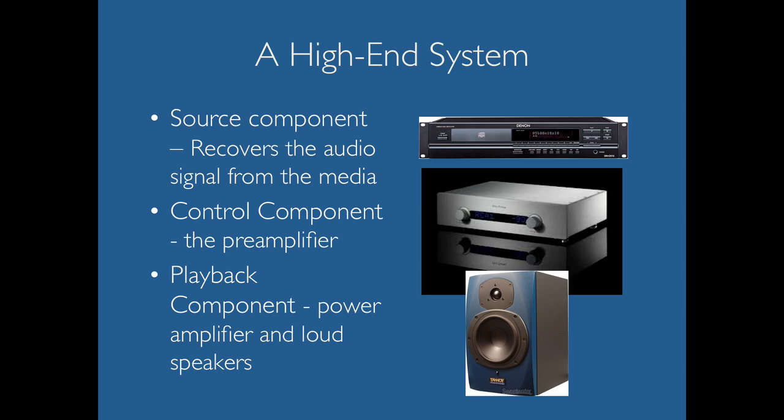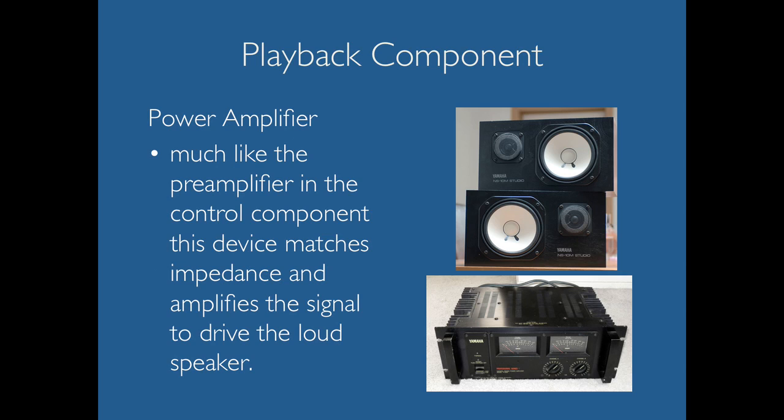So this could be both a power amplifier and loudspeaker, or it could be active speakers that have their own power amplifier within them. I show this picture of the Genelecs down here at the bottom. They are active speakers. They actually have a power amplifier within them. So power amplifier, much like the preamplifier and the control component, this device matches impedance and amplifies the signal to drive the loudspeaker. The Yamaha NS10s, as you can see here, a sort of studio standard for one reason or another, are actually passive speakers, so they need an extra amplifier, or a power amplifier, to actually drive the speakers.